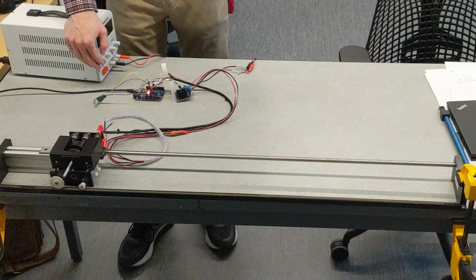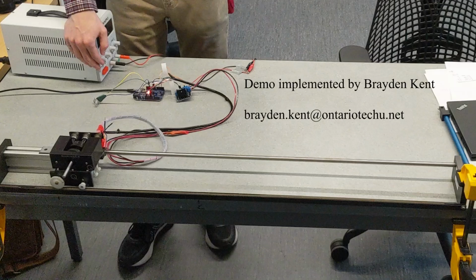The controller is designed to make the cart move to this desired position and stay at that desired position regardless of external disturbances applied to it. The current position of the cart is measured using a potentiometer that is connected to the motor. The potentiometer measures the actual position of the cart and sends that to the microcontroller. The input to the microcontroller is the desired position of the cart, that is 30 centimeters in this example.